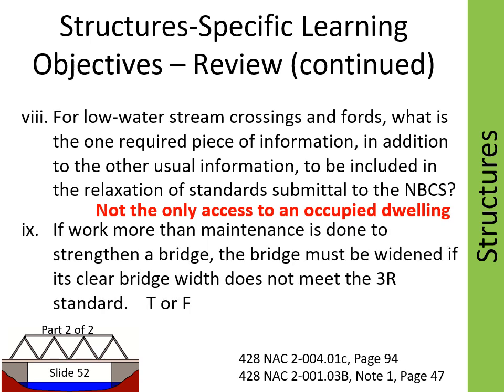Question 9. If work more than maintenance is done to strengthen a bridge, the bridge must be widened if its clear bridge width does not meet the 3R standard. True or false? The answer is true. The bridge must meet all 3R standards if work more than maintenance is done, or a relaxation of standards must be granted by the Board of Public Roads.